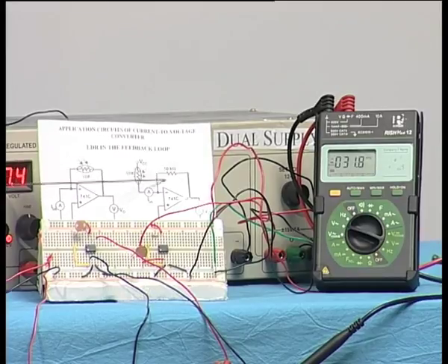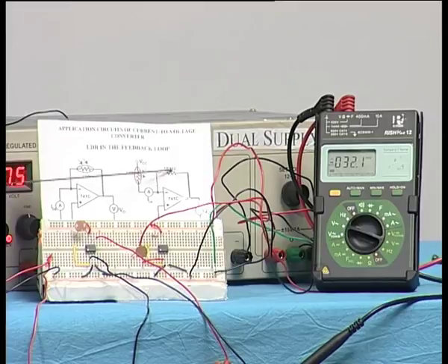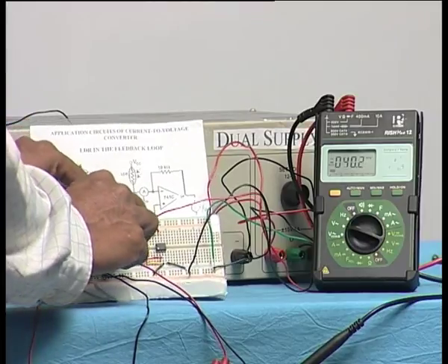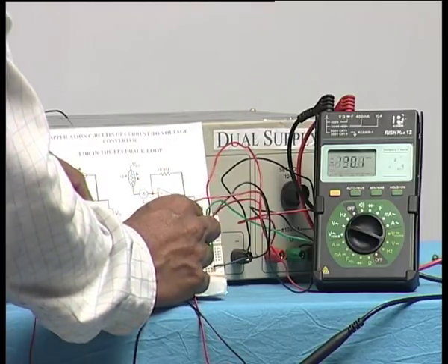input, and I have put a fixed resistor of about 10 kilo ohm in the feedback here, that you can see. This is the op amp, this is the 10 kilo ohm resistor, this is the LDR, and one end of the LDR is connected to the op amp, the other end is connected to plus 5 volts, and therefore it is energized with 5 volts. So now I will quickly change the multimeter from here to the next circuit.